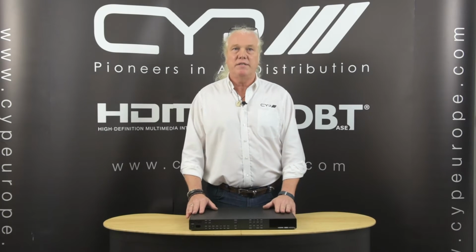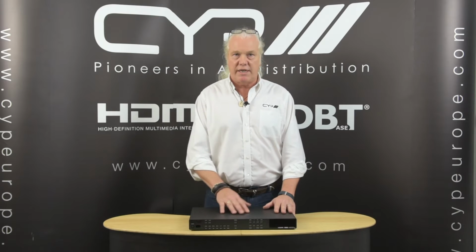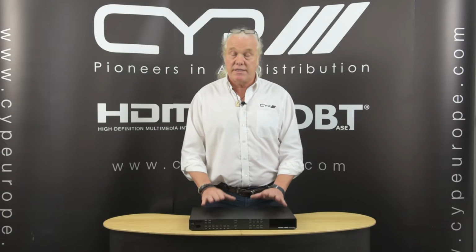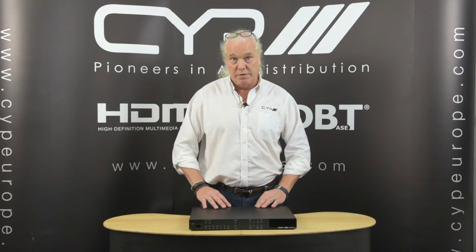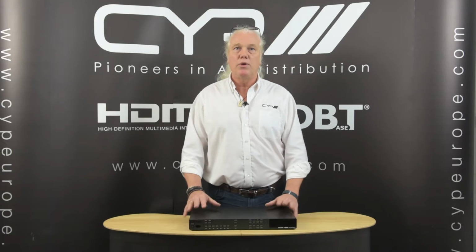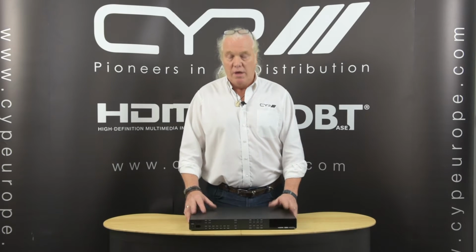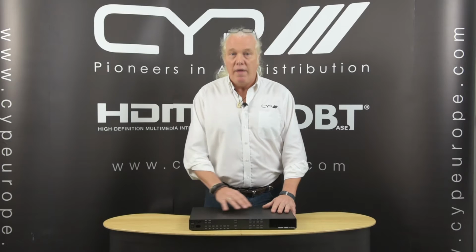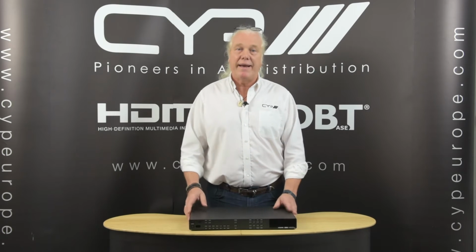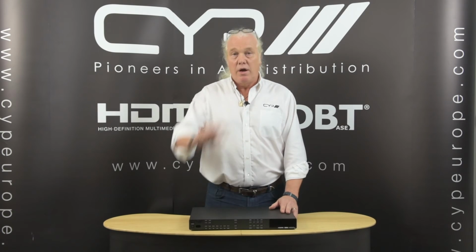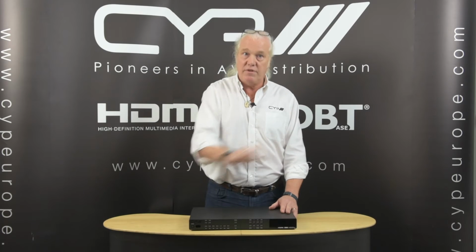Now the unit can also be set in switching mode. This means that any of the 6 HDMI sources are displayed simultaneously on the 2 HDMI outputs. Now in switching mode you can also have a picture-in-picture preview. This allows you to view any of the 5 sources that aren't selected on the main output in picture-in-picture mode across the top, side or bottom of the screen.